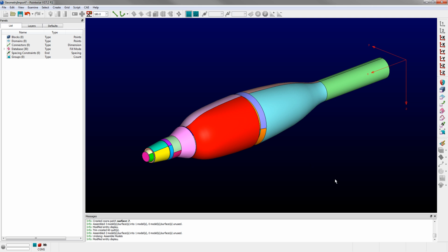And what that means is that each of these colors is going to get its own domain, and the boundaries of those colors are going to be connectors or grid curves. And that's how it's going to allow you to essentially extract or define a hard edge with a connector. This is really important because this is what quilts and models are used for, to help you define your surface mesh. So it's a very important concept.